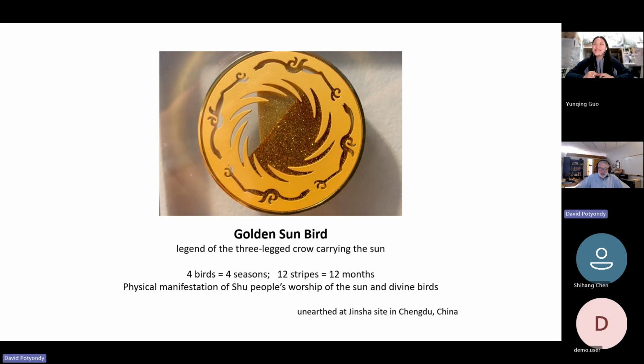This is a super good example of the two things people do with PFC. They do granular flow, things like this. Usually those systems are not sticky. They're just dry sand. They just flow. If you have dry sand, for example, any two grains cannot sustain tension. You have two grains of sand that are dry. If you pull them apart, there's no force. But if you push them together, there's a compressive force.